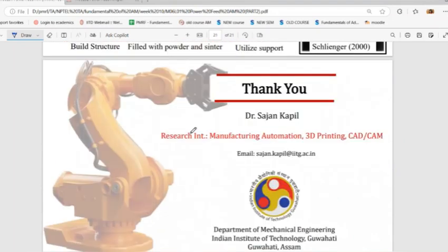One very important thing, as I am also working in the same area: powder DED is way tougher than wire DED because it's very tricky to control the process. It's very tricky to control the powder flow and minimize the wastage, because in wire DED the deposition efficiency is 100%, but in powder it's not like that, it's 30-40%.